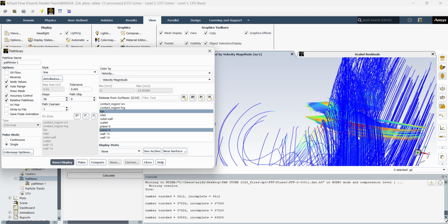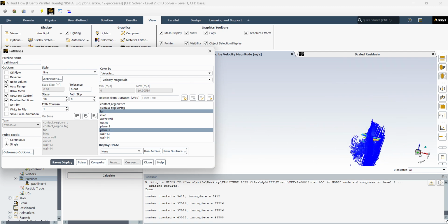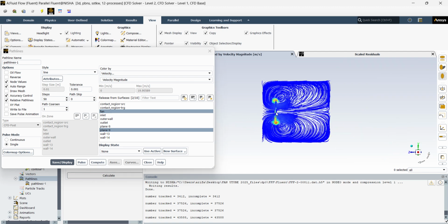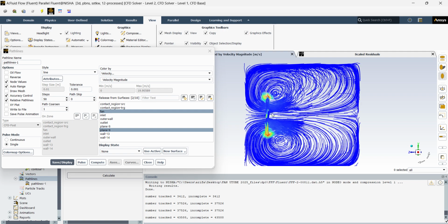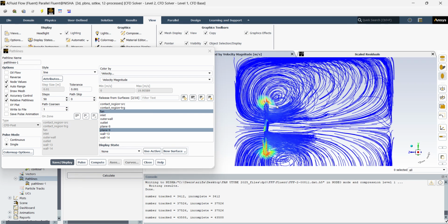Also if I display, now I will get the pattern on the airfoil, also on the vertical plane. Here it is coming in a different orientation. At the beginning itself, if you want, you can change the orientation. So this is the velocity profile. I have just stopped in between. Actually I have to refine the mesh, and run a little more, so that you will get different velocities in this streamline also.